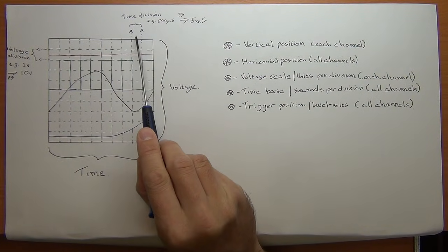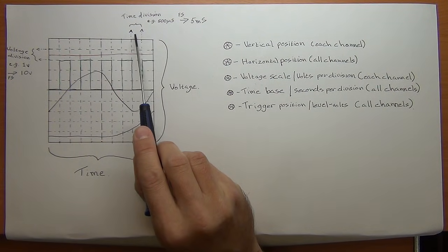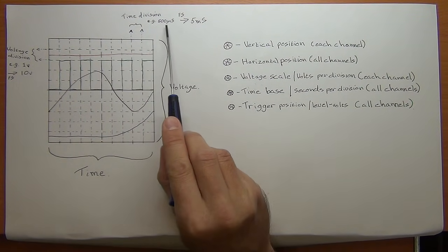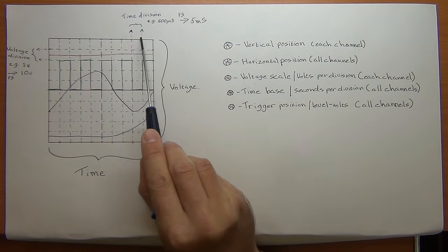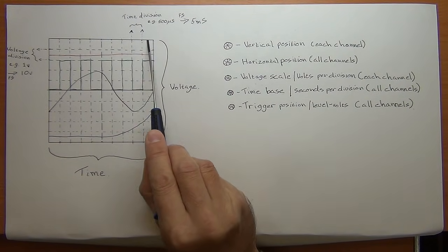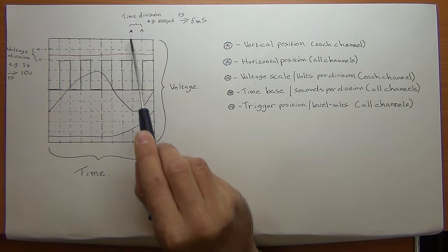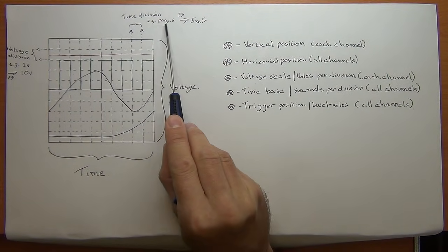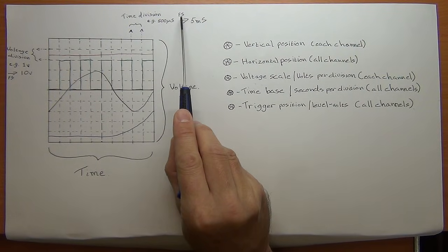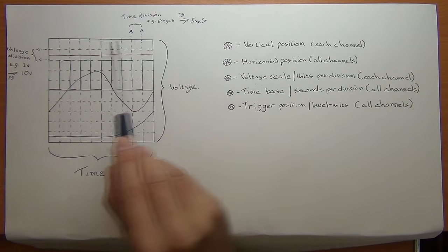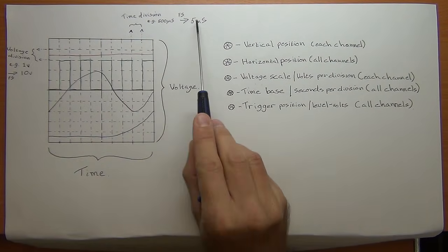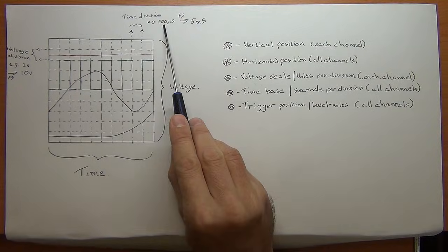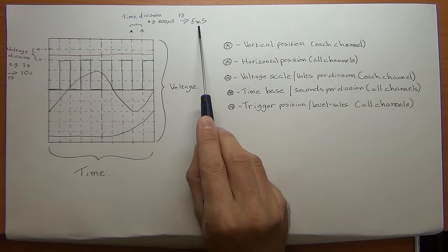And so, for instance, on your oscilloscope you may have it set to a setting of 500 microseconds, and that is a representation of each of those little segments. Now, if you happen to have it set at 500 microseconds, then in essence your full scale reading, and when I say full scale, your whole time base that you're showing in that screen would work out to be obviously 10 times that, which would be 5 milliseconds.